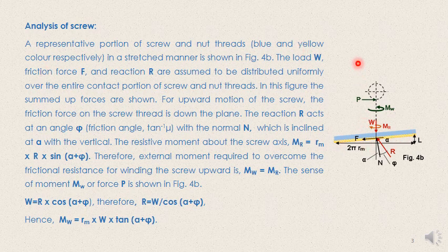So what is happening due to the load W? The contact is taking place at the lower side of the screw thread and the upper face of the nut thread. This representation is given for one full length, that means we have just stretched it. But this could be much longer, as much as the contact between the screw thread and the nut thread.